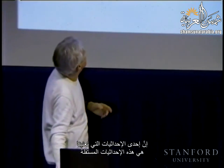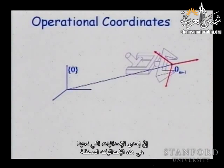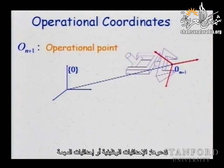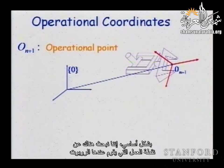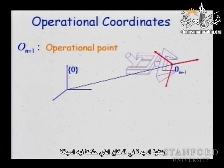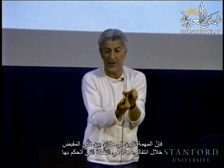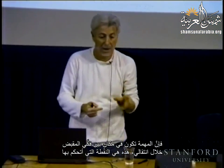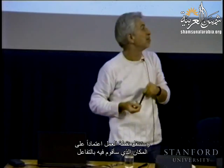So a particular set of coordinates that we are interested in is this set of independent coordinates. We call them operational coordinates, or task coordinates, essentially there we are looking at the operational point where the robot is acting, where we define the task. So for instance, if I'm going to grasp, the task is somewhere in the middle between the two jaws. As I move, this is the point I'm controlling. But if I have a tool, the task will be here, and the operational point would move depending on where I'm going to do the interaction.